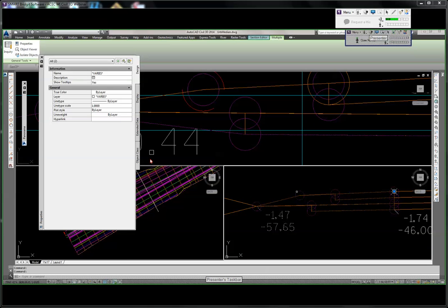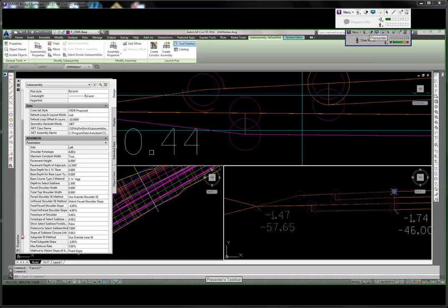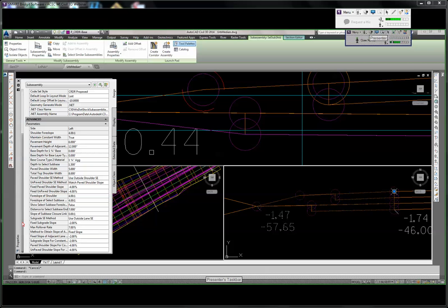I have two things selected there. There we are. If your properties window is ever empty like that, it's either the graphics card not keeping up or I had two things selected, so that was really my problem. I'm going to scroll over there, scroll down, and towards the bottom, I'm looking for a field that has 0 to 1 as the slope, because that's kind of an odd thing to see.